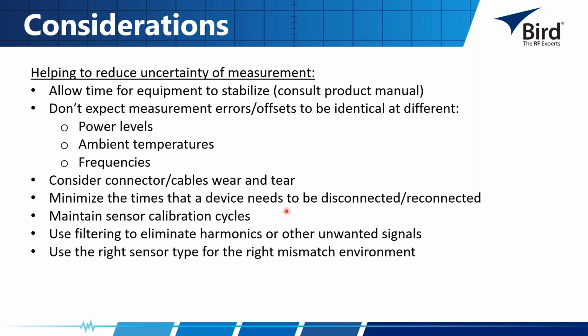This could be particularly interesting on the more precision process side of things. I know different guys on the semiconductor side who are using matchboxes. There can be some filtering techniques. Even just creating a good match over a smaller frequency range can result in the powers that are actually getting through being what is desired. Some of the others are going to be filtered just by the nature of the matching network.